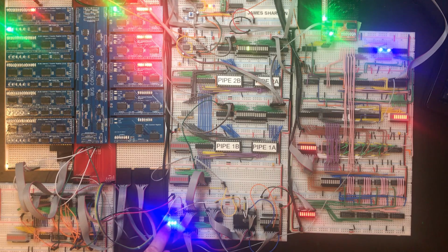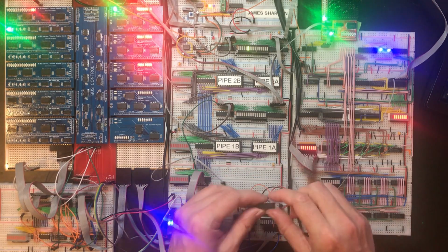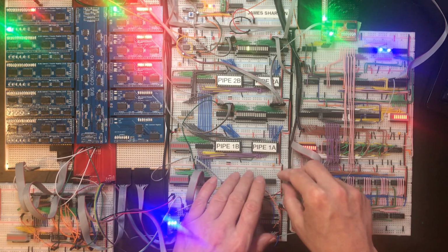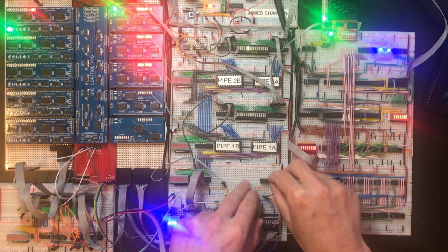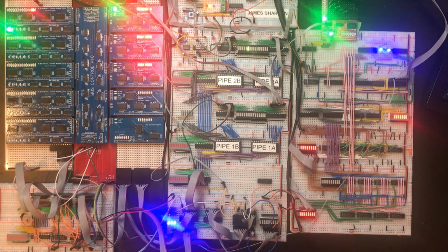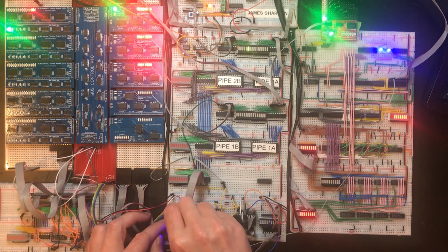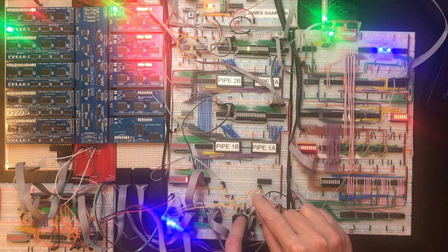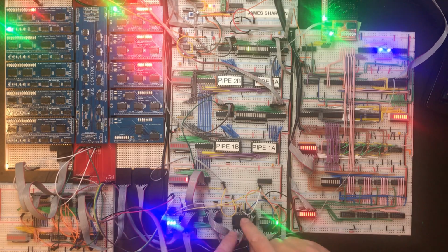Now if you think about the direction line here, when that goes off is when we're trying to assert something onto memory data. And so this output enable line needs to be the opposite of that direction line. So this is our old friend 74LS04. And I'm going to chuck one of these in here for now. I need to use some of this space for a circuit later on, but for now that can go there. So I've taken the direction line and I pass it inverted into the output enable line of the ROM chip.